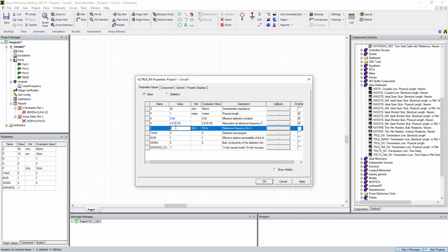So that's just due to the conductor. We calculated tan delta using that little formula I came up with, 3.51, and we're going to use non-causal. Okay, so this should create the same attenuation using this different model. This is just a generic transmission line model where we specified the attenuation due to the conductor and the dielectric in a slightly different way.